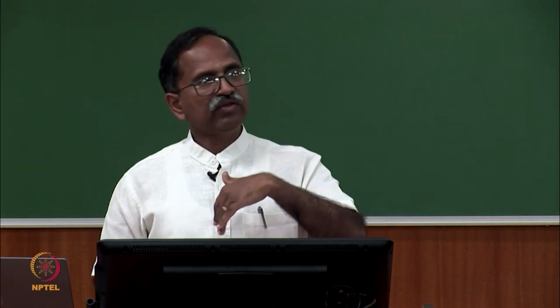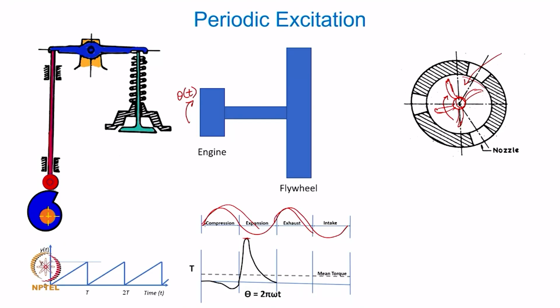Once in one rotation, if you focus only on one blade, because one blade itself is a vibratory system, it is a cantilever, isn't it? A blade is nothing but a cantilever in action. Now, think about that blade making one rotation. In one rotation, each blade is going to be subjected to how many such pressure perturbations or force impacts? 3 times, depending upon the number of nozzles.